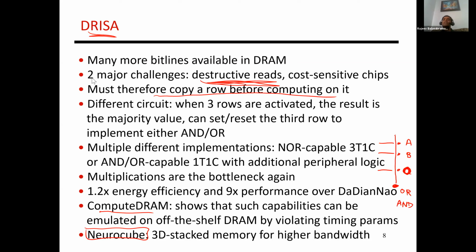So this third question is asking, are we using near memory approaches instead of a dedicated accelerator, or integrated into the CPU? Many of these early papers are somewhat agnostic to that choice, but they do have a vision for how you would use it. At least the compute cache and the neural cache works are saying, let's take a traditional CPU. You can add a separate accelerator to it, or you can just take advantage of the fact that the CPU has 10 megabytes of SRAM sitting around.